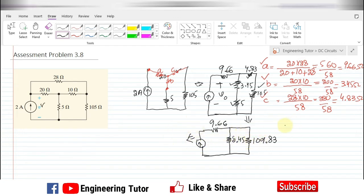Okay, so let us convert them again, because now 8.45 and 109.83 are in parallel combination. Their R prime will be equal to 8.45 multiplied by 109.83 whole divided by 8.45 plus 109.83.